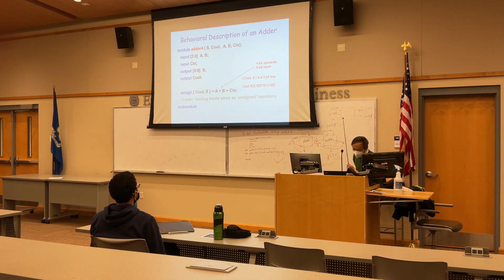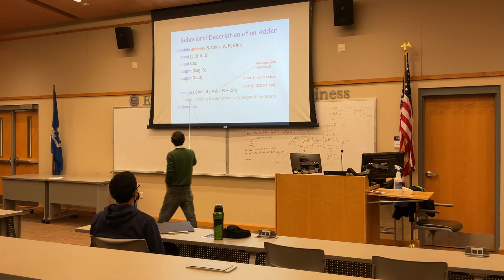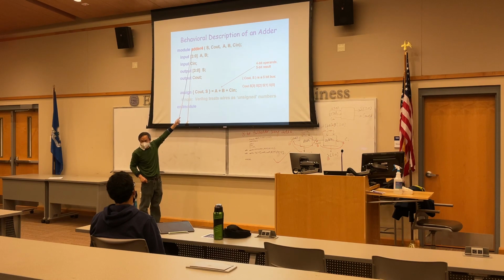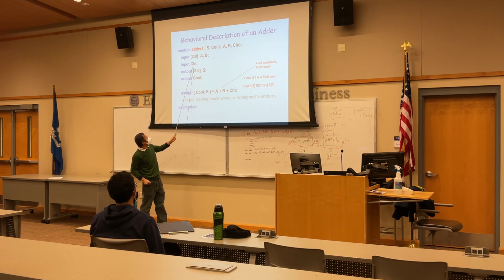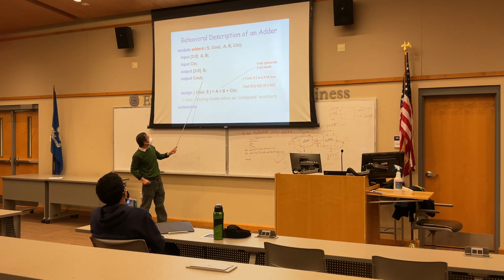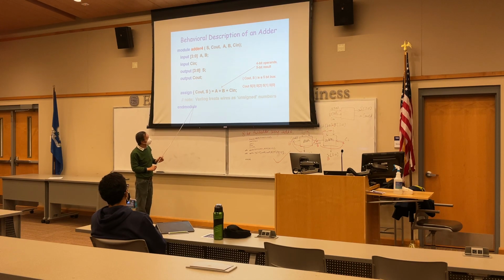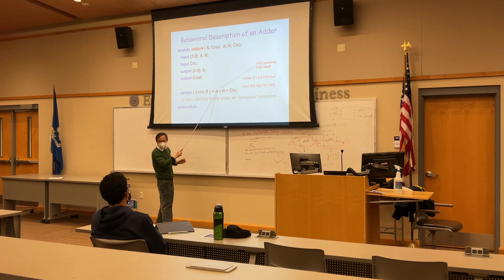And this one, the adder 4, we can also assign. How? Input declaration: module name, port list, input, output. This is the 4 bits, bit 3 to bit 0. And then C out, output, 1 bit. And then assign. What are we going to do?